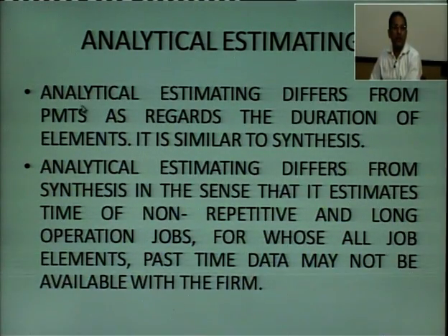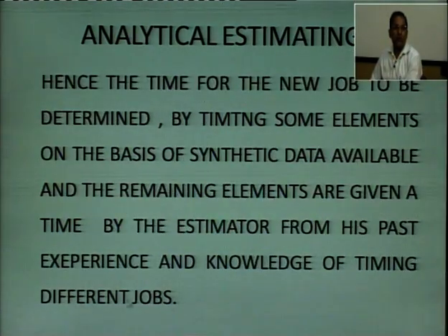Analytical estimating differs from PMTS as regards the duration of elements. It is similar to synthesis. Analytical estimating differs from synthesis in the sense that it estimates time of non-repetitive and long operation jobs for whose job elements past time data may not be available with the firm.